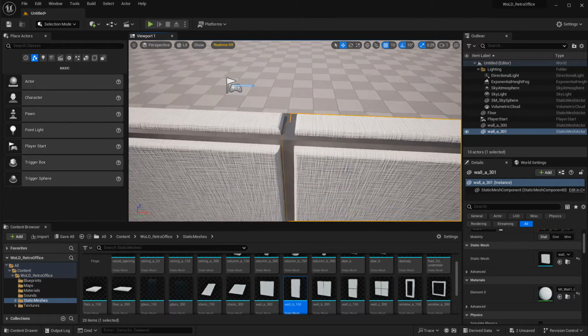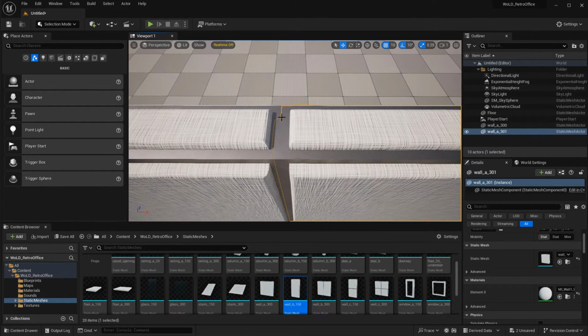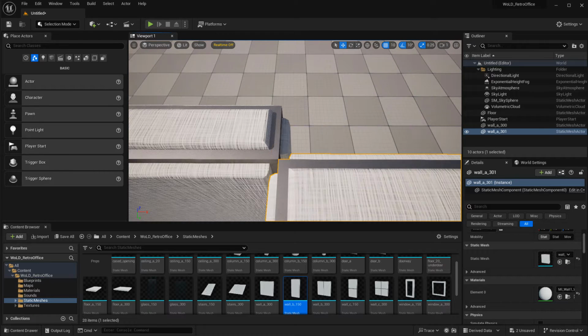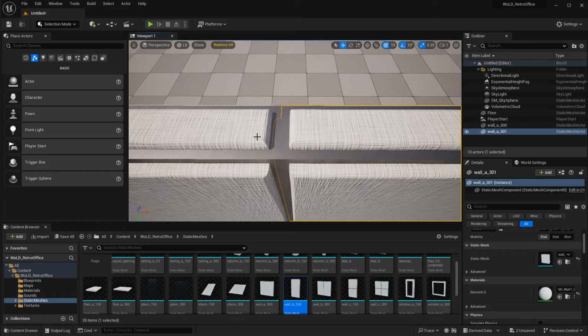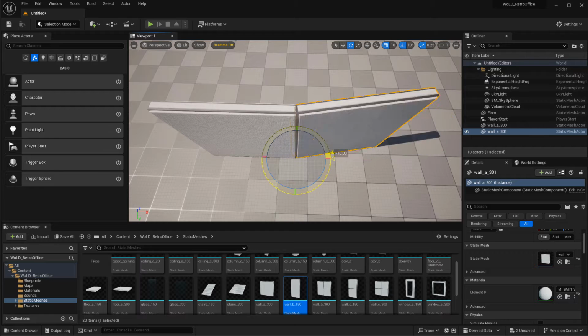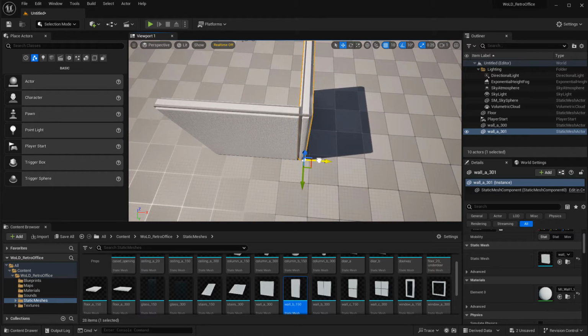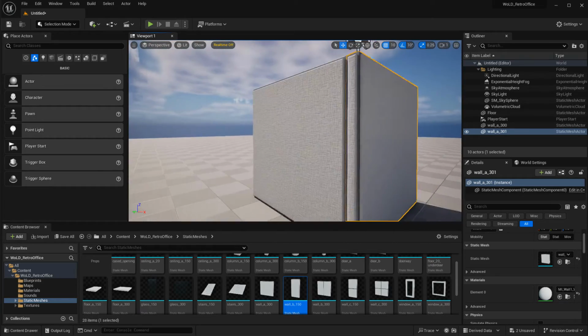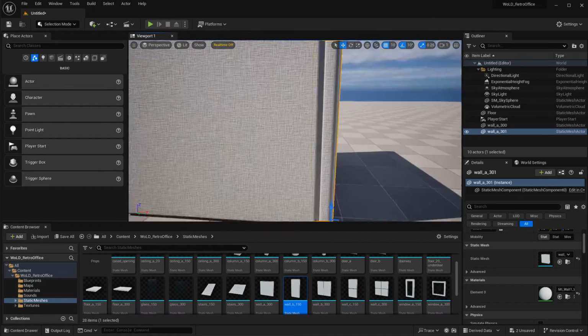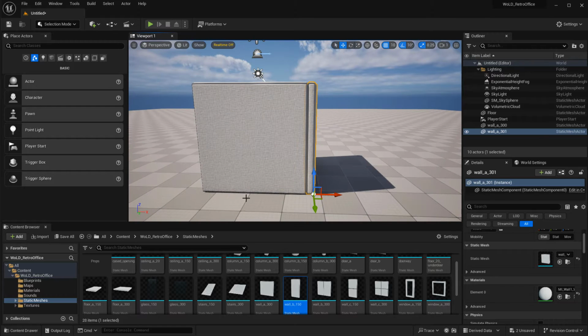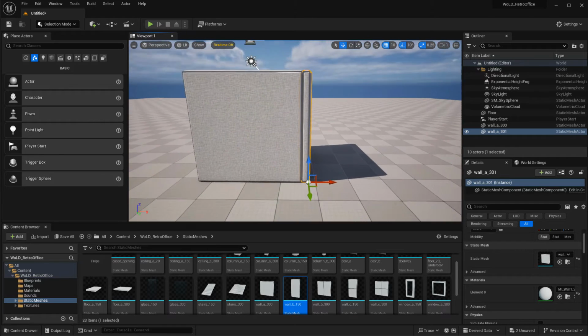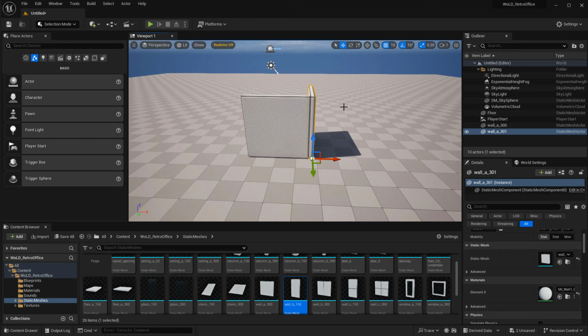However, you will find the little extra piece of geometry, it's not going to create any problems, but you can see that little piece of geometry right there is actually overlapping into the wall, and that's how it's supposed to be. So again, as long as you stick to the 10 unit grid system, everything will be just fine. But what it allows you to do is have a little extra geometry whenever you're placing two walls together like this. You have nice little detail on the corner, and everything lines up properly. And with the floor and the ceiling and everything else will be perfectly together for you to create a more modular environment a lot easier.